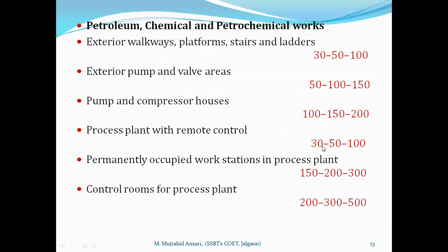Similarly, for a process plant with remote control, nobody is going to operate over there, so it is not necessary to have a higher illumination level. We can use 30, 50 and 100 lux, just similar to an interior platform, walkway or staircase.